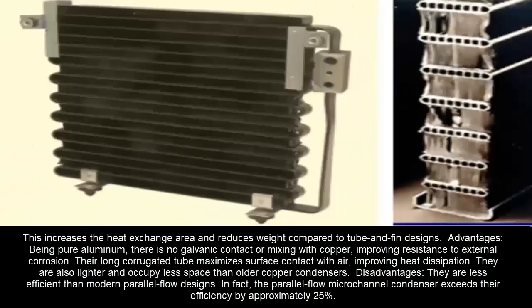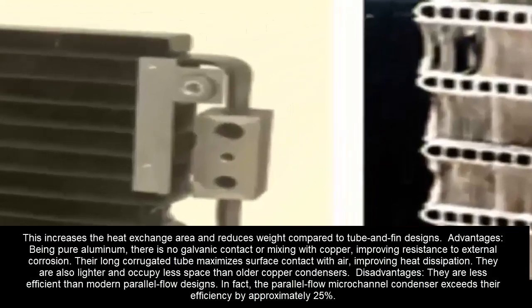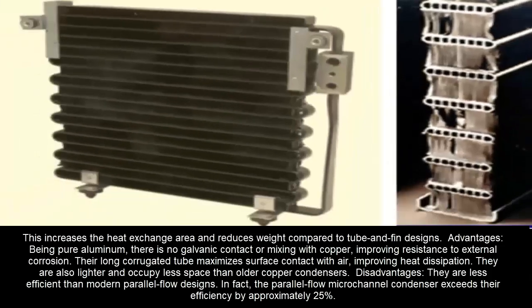Their long corrugated tube maximizes surface contact with air, improving heat dissipation. They are also lighter and occupy less space than older copper condensers. Disadvantages: they are less efficient than modern parallel flow designs. In fact, the parallel flow microchannel condenser exceeds their efficiency by approximately 25%.